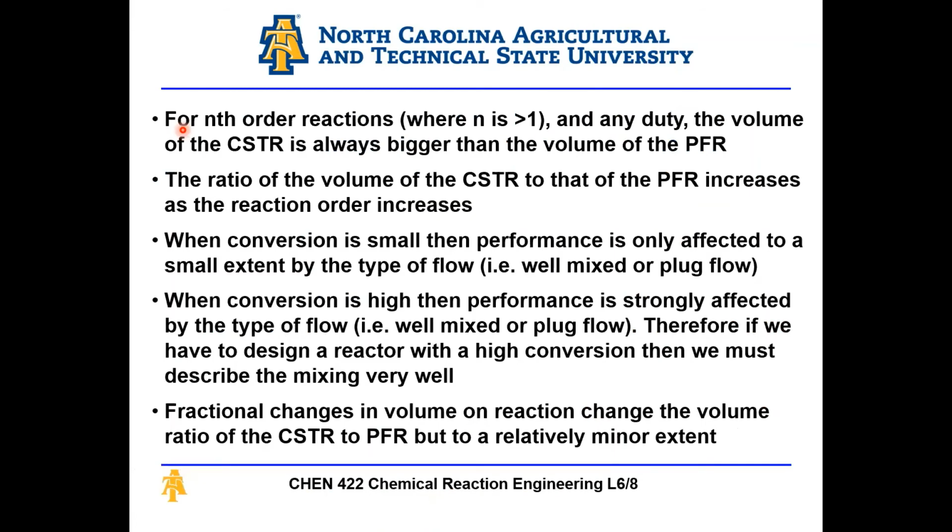So these are the conclusions for nth order reactions where n is greater than 1. In any duty, the volume of the CSTR will always be larger than the volume of a PFR, right? The ratio of the volume of the CSTR to that of the PFR increases as the reaction order increases. So if you recall, we did it for n equals 2, n equals 1. You can see that n equals 2 required a much higher ratio of volumes.